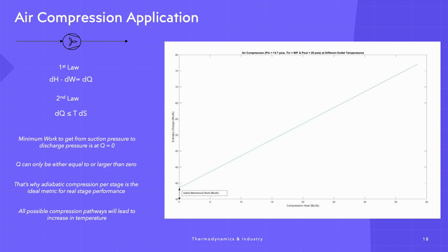Absolutely. Someone might be thinking as well, hey, there is the isothermal compression. It should be better than both of them. Right. But if you technically look into it, you're going to find the compression stage, then you're going to add the inter-stage cooling. It's true. The isothermal is going to be if you have more than one stage, and you make the stages so that you don't want to get to that bigger pressure issue.